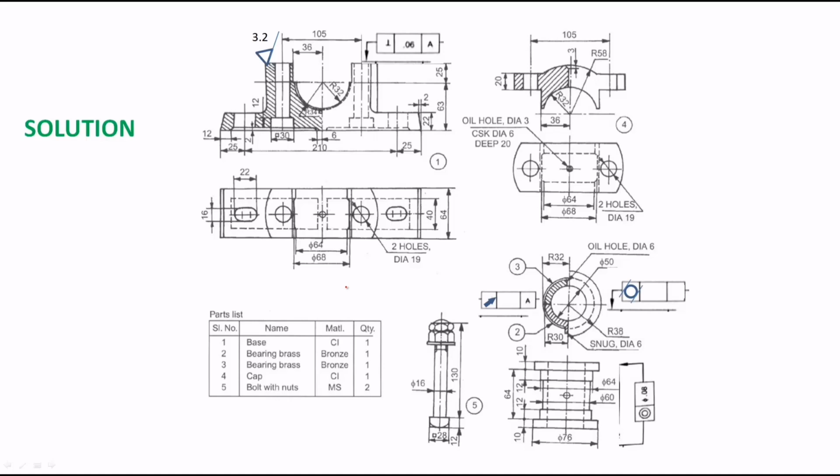So drawing this component figures means individual parts alone. After enlarging or drawing these individual parts, we need to indicate the surface roughness values and surface roughness symbols, tolerance symbols, and we need to prepare a process sheet and a type of fit table also. These are very important.